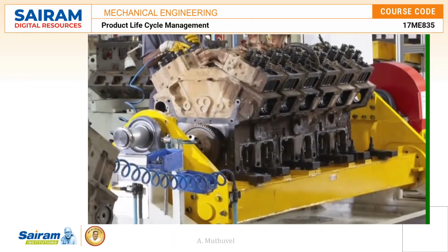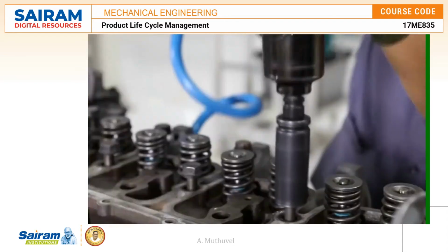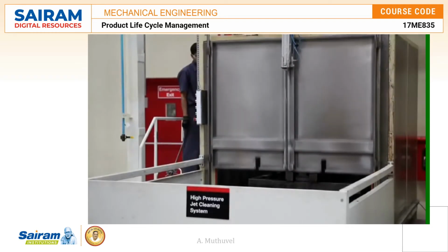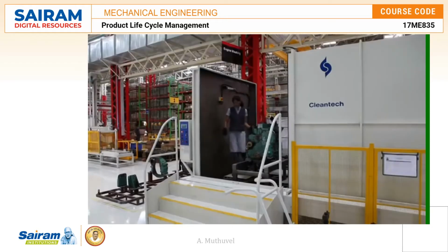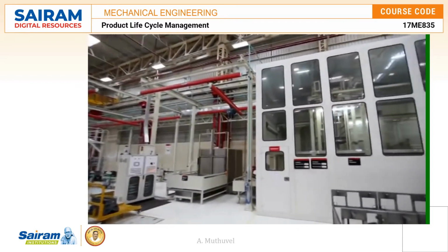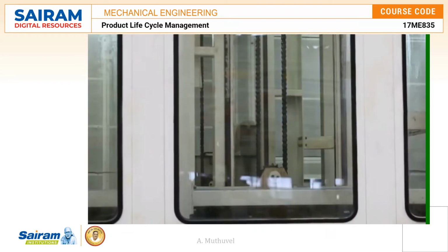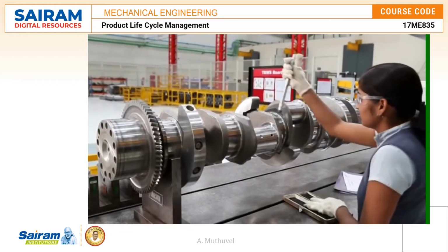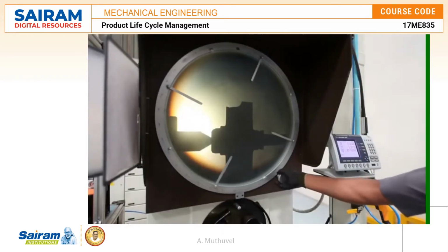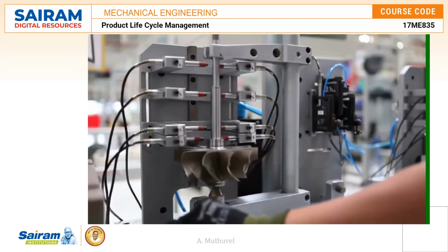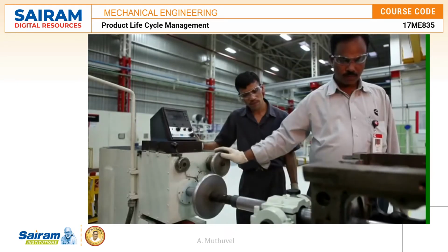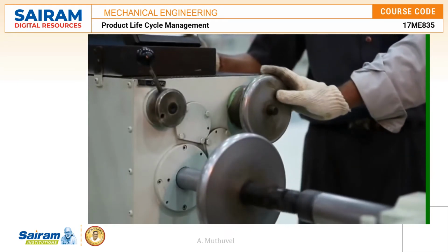The incoming core is completely disassembled down to the last bolt, and every individual part is cleaned using the latest appropriate technology with non-abrasive cleaning systems that do not eat away critical metal surfaces. This is an important difference between the Cummins process and the process followed during repair. After the cleaning process, certified measurement equipment is used to inspect every part to ensure that it meets original factory specifications. If a part cannot be restored to factory specifications, it is scrapped and replaced with a new genuine Cummins part.